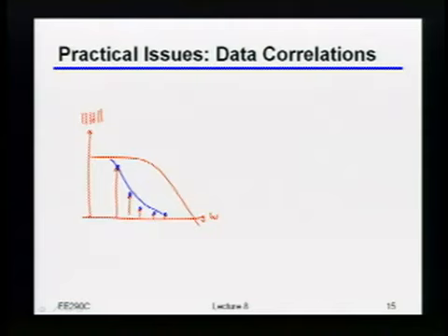which you can imagine that if all of a sudden you don't send a square wave anymore, you send actual real data, now you're in trouble because you're completely misequalized, right? So this is indeed a practically fairly significant issue to worry about, especially if you look at systems that put some coding onto the data. For example, something like an 8B/10B code, which just guarantees transitions. But inside of those codes, they usually have specific patterns that are there just to tell you, oh, actually, I have no real data. I just have an idle sequence.